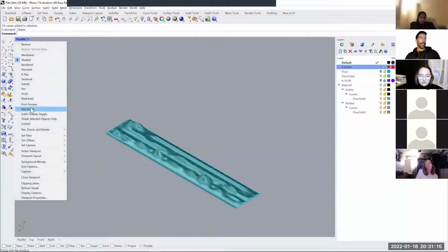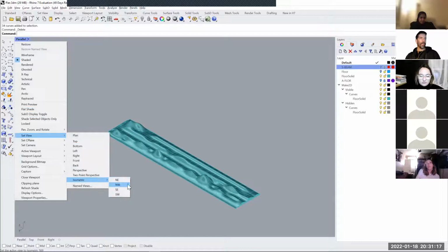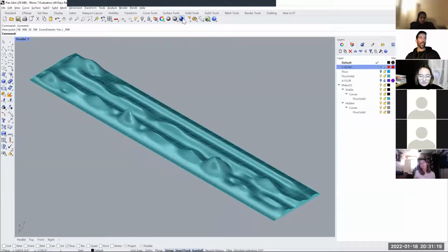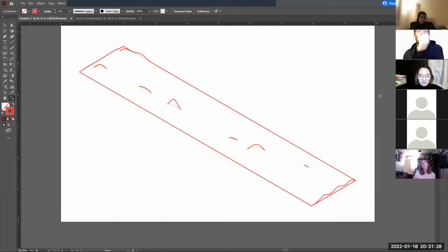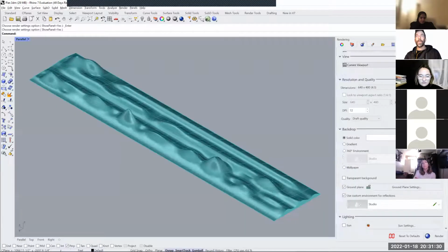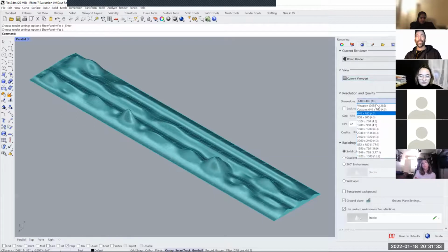From the same view, northwest, I need to do a render with the blue button, and you're going to do a little bit better resolution. So you're going to actually select viewport, just a little bit bigger, 2000, whatever. Pixelation, you might want to have this 150, and then this to good at least or final.